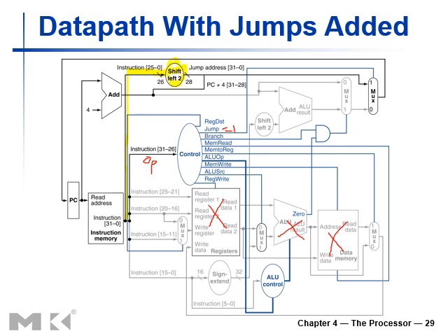that are converted into 28 bits, and here we are taking the most significant nibble of PC plus 4 and concatenating it in a circuit. So definitely this is not a direct connection the circuit suggests. It's basically a concatenation operation here.